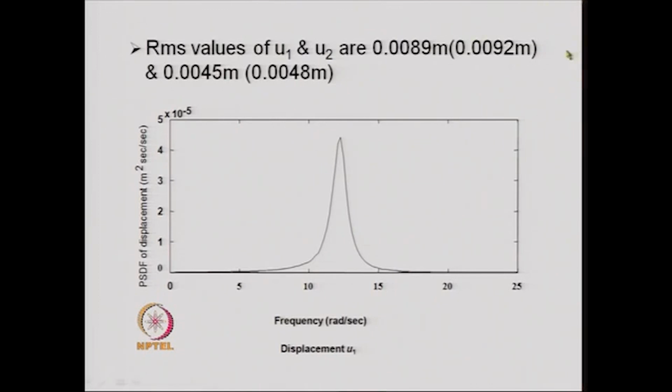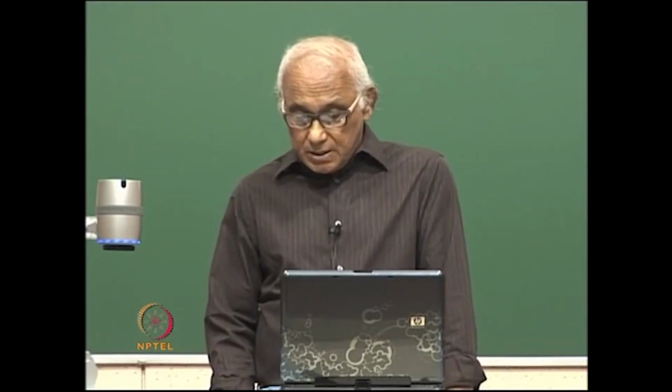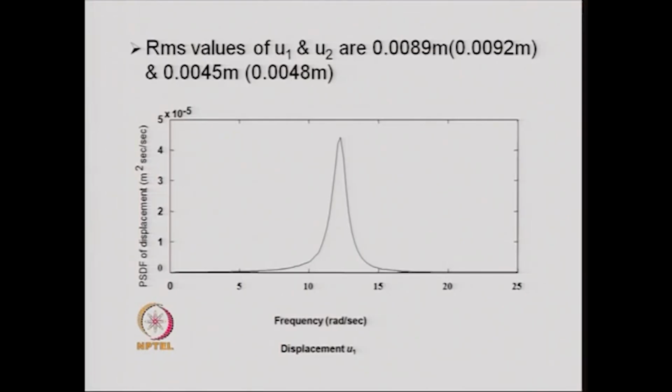The time history analysis that we obtained for the El Centro earthquake. Note that the power spectral density function input that you have given here is the power spectral density function of the El Centro earthquake, which is tabulated at the end of the book as an appendix. One can use those digitized values. So, we have used those digitized values for obtaining the power spectral density function ordinates at different frequencies.